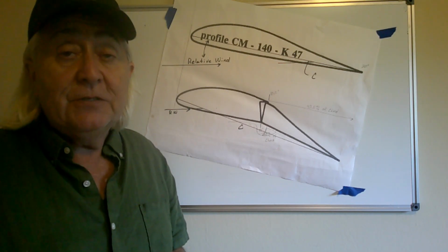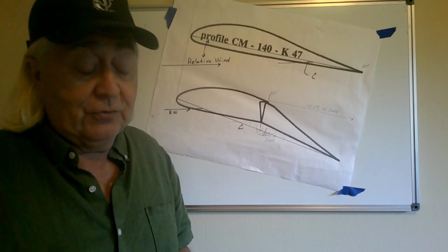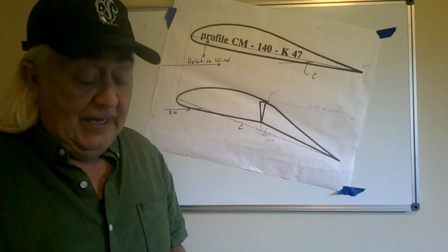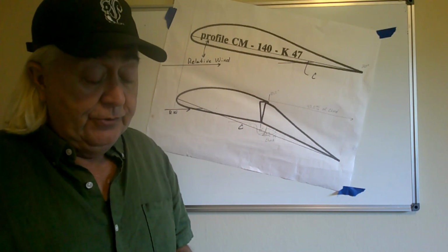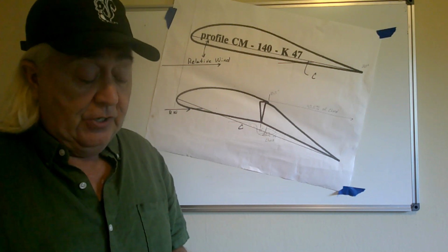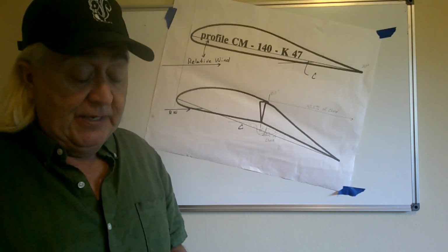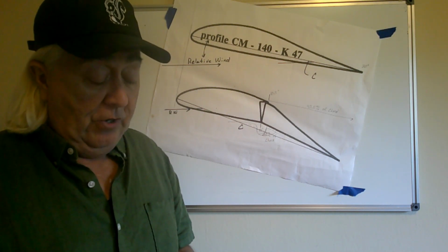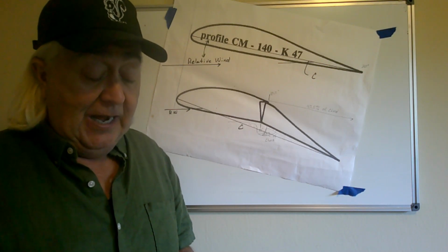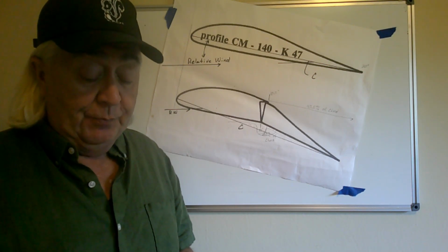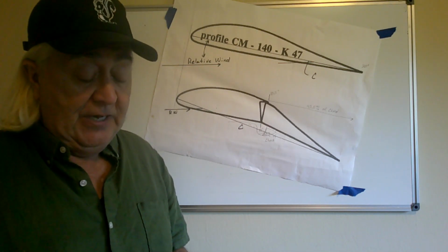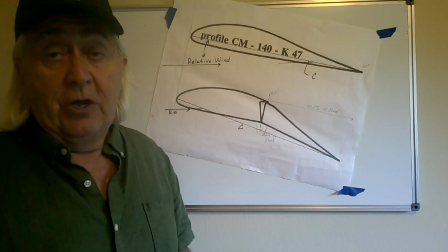At most, and their flap's only 20% of the chord, not half. At most, some pilots have a hard landing due to dropping the flaps when flying slow in ground effect, but this hasn't been a problem with the Swift. All bets are off with the Flair 30 since I don't know what their flap was doing in flight. It seems like any flap deployment would cause a huge nose down trim, as would a stall.